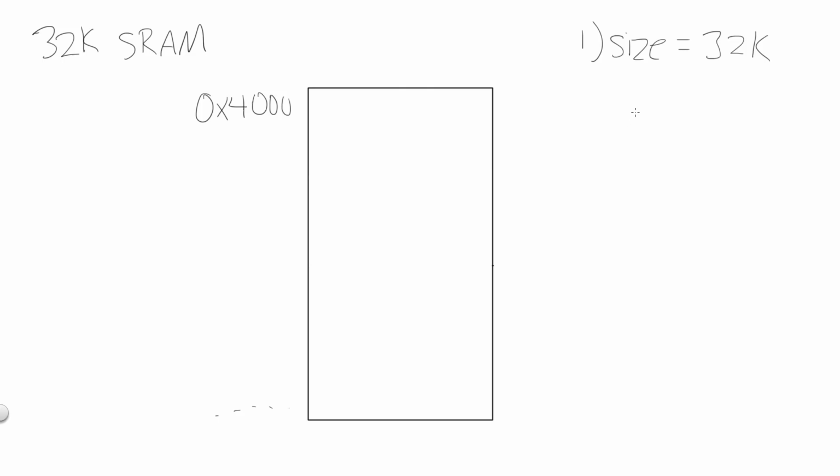For example, if I was told I had to make an SRAM start at address 4000, I would have to explore other options, such as using multiple smaller 16K chip selects to enable one device, since a 32K chip select would not be able to be placed at address 4000. There are many other possibilities like this, some of which will be exemplified in the following video.